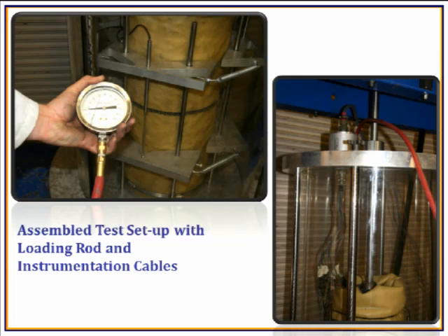To check the vacuum pressure, I mean whatever pressure that we are intending to use during the whole testing, like shear strength test or repeated load testing, we can also keep an eye on the pressure level with the pressure gauge that is installed at the base plate.